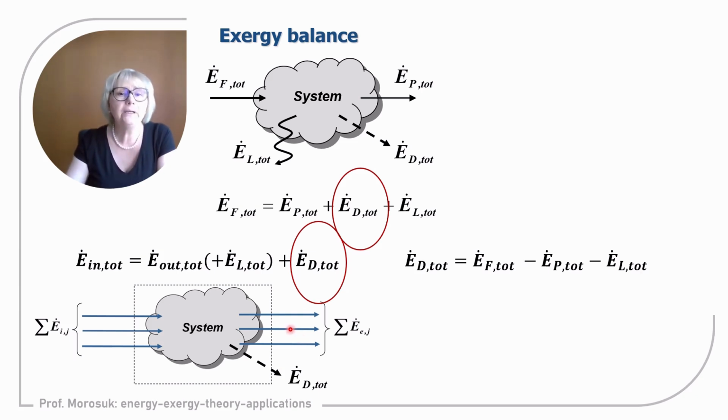So we can also proceed with the evaluation of the exergy conversion system using the concept of exergy of fuel and exergy of product. And definitely the value of exergy destruction, regardless of the approach, will be the same. Therefore, if we would like to calculate exergy destruction of the entire system, then the proper definition will be exergy of fuel minus exergy of product minus exergy of losses.